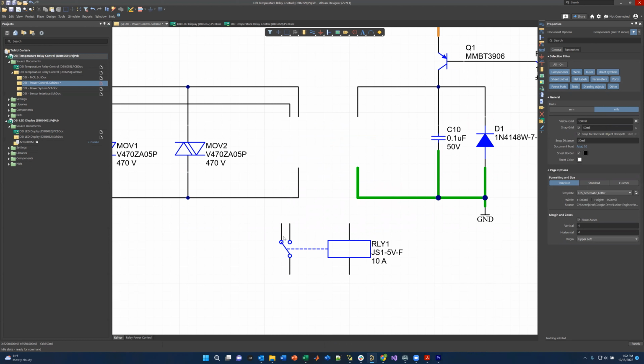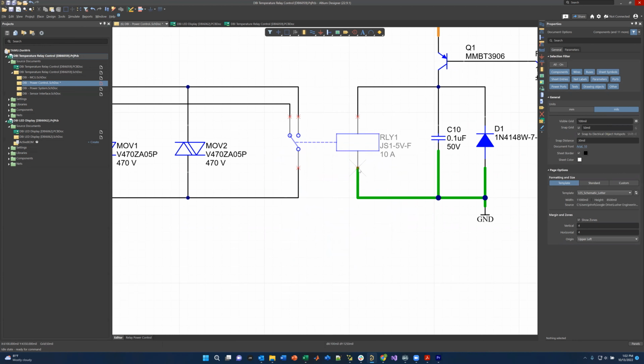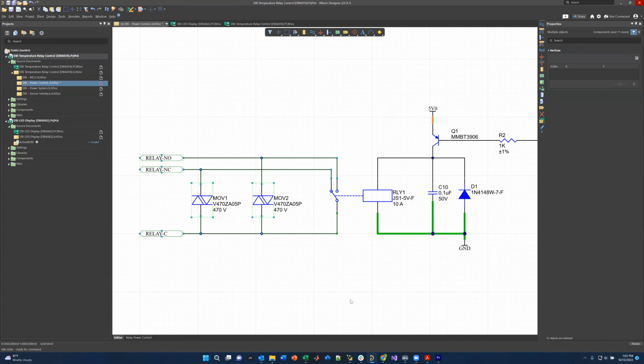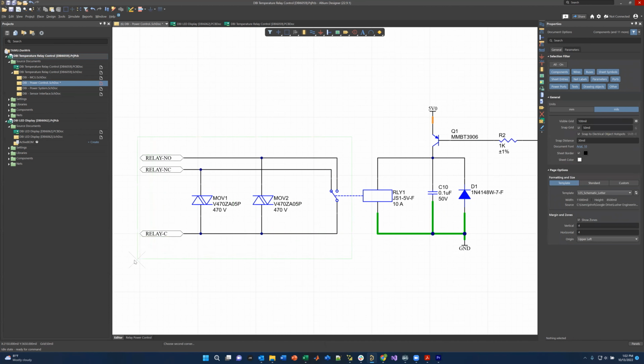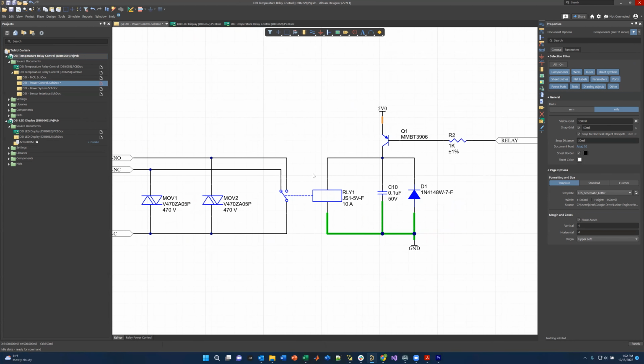This is the normally closed, and then when it's powered, this plunger will push in because of the magnetic field, and the normally open contact will be shorted. So we have the live or power section. This is the power we're controlling. It is completely isolated from the rest of the circuit. There is no electrical connection between this side of the circuit and this side of the circuit. The magnetic field in the plunger is the only interface.